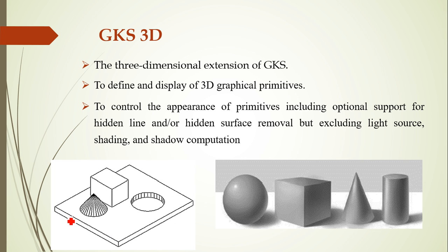Again, this 3D model could include some surfaces. So the major appearance of this surface will be controlled by the GKS here. GKS helps in providing a good appearance for these images. So various shading methods, various coloring methods you could utilize. That is what is meant by rendering. So for that purpose, extra primitives are available in the GKS for providing good appearances such as coloring, shading, proper rendering, and so on.